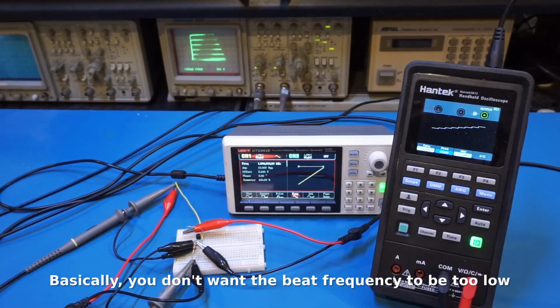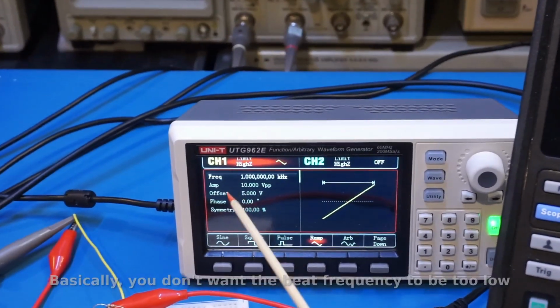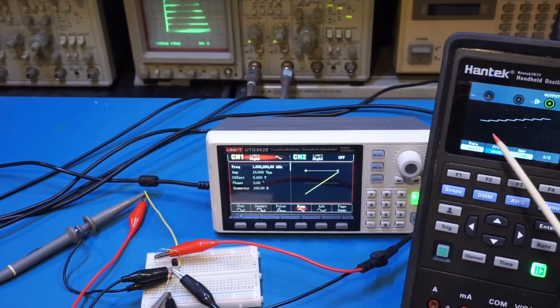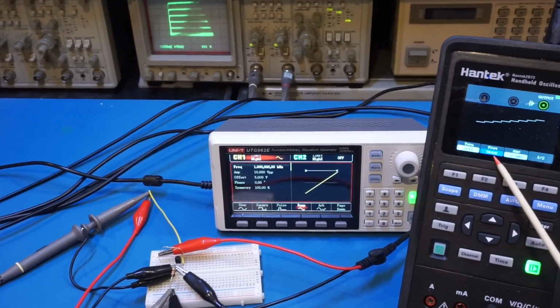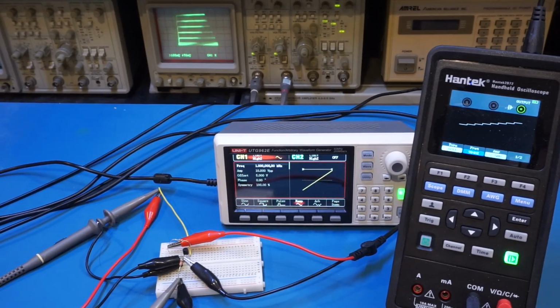If we take a look at the frequency setup here on the 962E, you will see that currently we set it at 1 kilohertz, and the signal output from the Handtech is currently set at 984 hertz. This ensures that these two frequencies do not generate a beat. Otherwise, you will not get a very nice looking image, as I will show here.